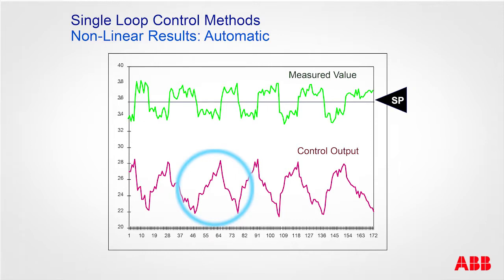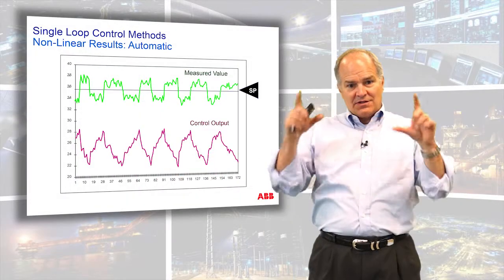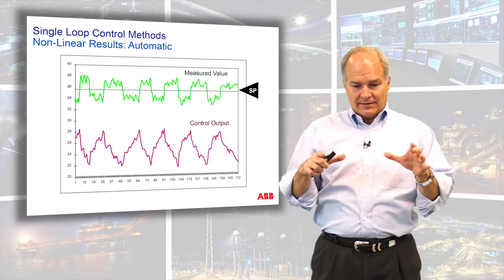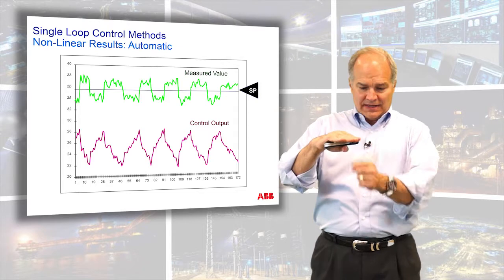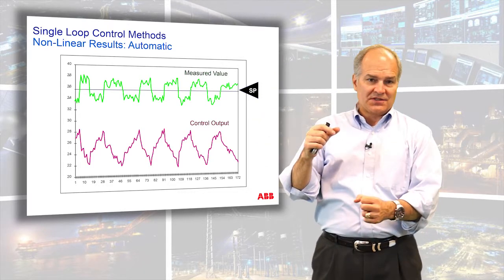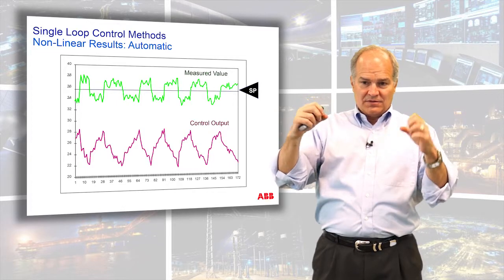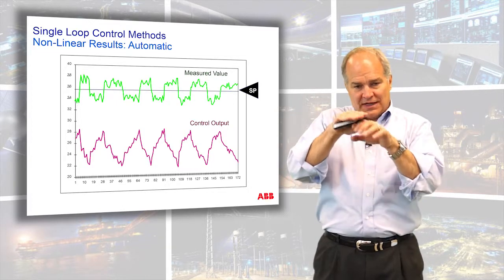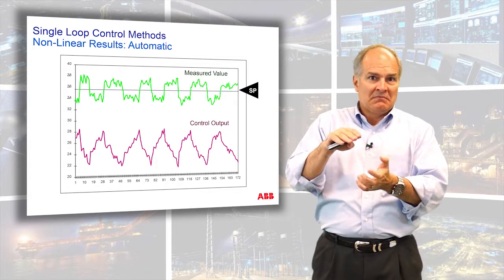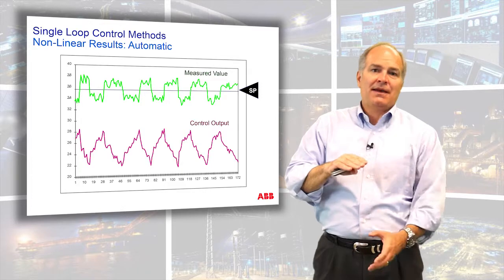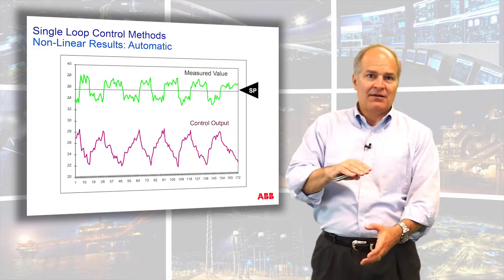If you can imagine a single-seated globe valve, the top hat has a diaphragm connected to a shaft, and you're filling air in it. So let's say the shaft is rusty. Now you're filling it up, you're building air pressure, and it's trying to push on that stem, but there's rust in the way. And then all of a sudden, the air pressure builds, and it jumps right past the rust, and it says, okay, now I'm there.